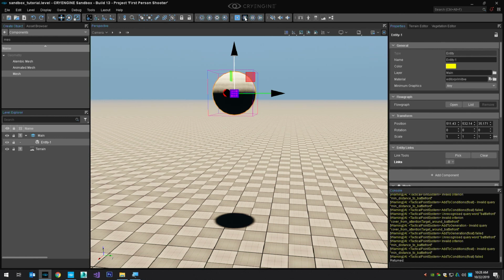Gravity has now been turned on. All the physics are on. Why is the ball not falling? It's a model, but it has no mass. It's not what we call a rigid body, and it's not a soft body either. It has no physical properties other than the definition of this mesh. So let's fix that. In order to change that, we're going to add a rigid body component.